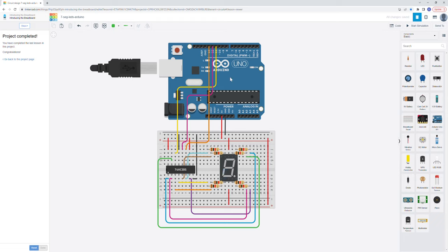We have coded the Arduino to display digits from 0 to F in hexadecimal base, and each time, by defining a for loop, we define the exact coding to the shift register. It's latched inside the shift register, and then it's driven into the 7-segment display.